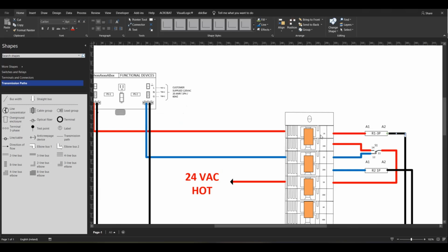When the 3-pole relay is energized, the 1B terminal, which is the second terminal, will act as a hot terminal, and that is connected to pole 11, which is connected back as an output on terminal 3B. So that will be your hot terminal from the relay, and that is used as the hot on your controller as well.